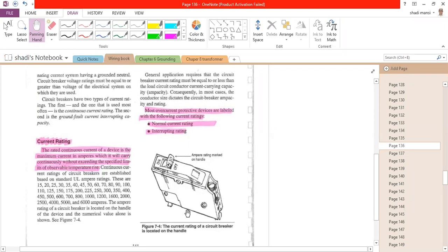Let's assume that it works with 120, by the way. You have to put the voltage also into consideration. Now, 120, 30 ampere, so it can handle the 30 ampere all the time, continuous 30 ampere without raising the temperature. Here, I want to pay your attention to the fact that sometimes we have bad electricians who put any kind of circuit breaker, or we have these ignorant people who add load to the same circuit breaker without changing the circuit breaker. Assuming that this circuit breaker goes to the kitchen after you calculated the load that it needs to be done in the kitchen.